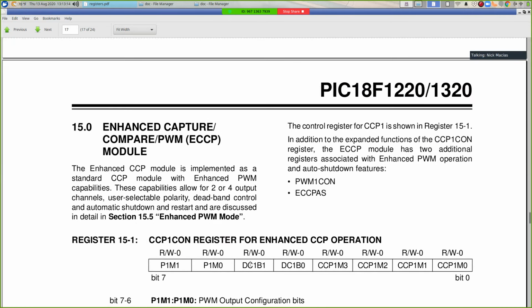Alright, why do they do this? Other than the fact that sometimes it's nice not to have to worry about resetting your timer register. This goes into what's called the ECCP subsystem, Enhanced Capture Compare Pulse Width Modulation module. And this is another thing that most modern processors have, something to support these kinds of functions. So PWM is the one we want to talk about. There is hardware support inside the PIC chip to automatically generate pulse width modulated signals.